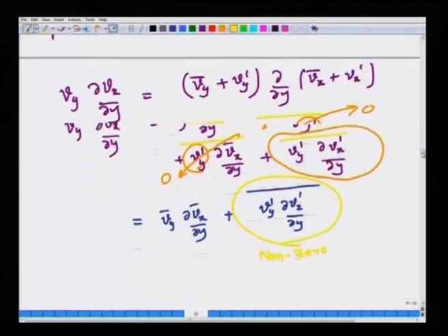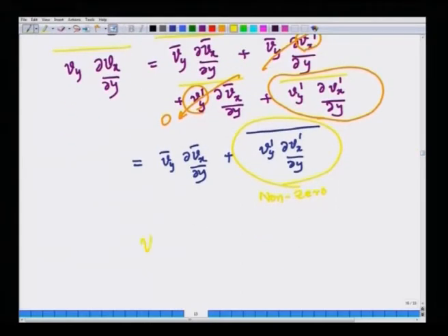And in general such a quantity cannot be 0, because trivially, if you look at quantities like Vx' times Vx', and you average it, Vx' is either positive or negative. So if you square it, it becomes always a positive quantity. This is always greater than or equal to 0. So obviously, in such cases where you have quantities like Vx' multiplying by itself, we trivially see that the time average of that quantity, even though it involves fluctuations, is not 0.